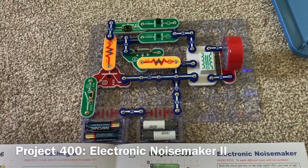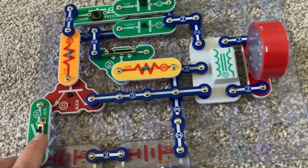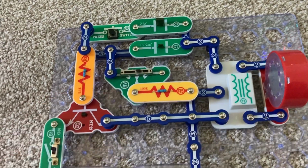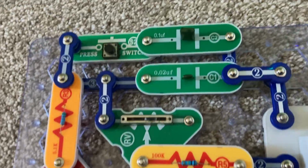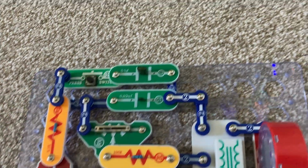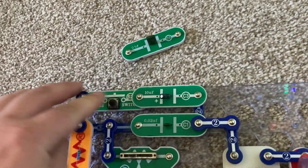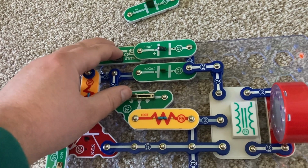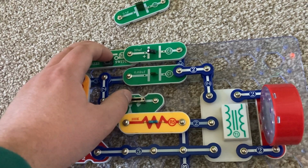For electronic noisemaker 2, I replaced the R4 resistor with the R5 one. This also changes the tone's frequency. I can also still replace the C2 capacitor with the C3 one. Now, the frequency is even lower with the R5 resistor than with the R4 one.